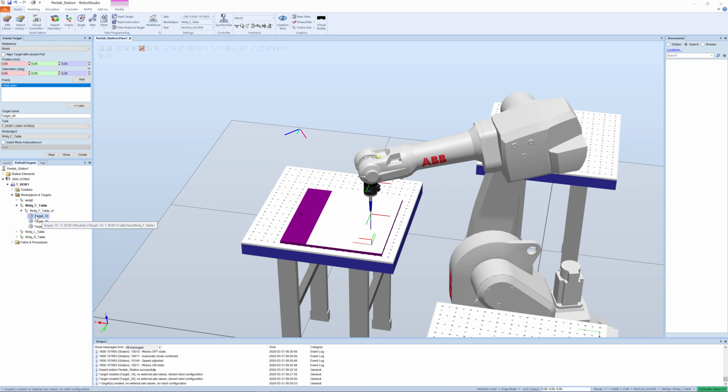the via position and the approach. We can actually keep it as it is. But if we would like to, we can rename those. So this could be the home position, like this one, and this could be, just click one more softly, it will pop in the rename, via pos, and that one could be the approach paper, for example. So we know what we are doing with these.